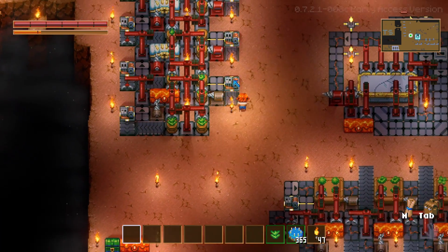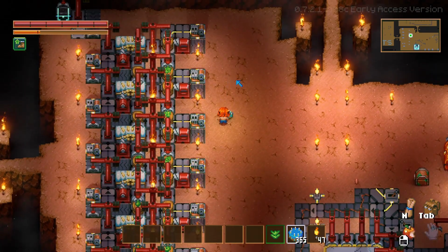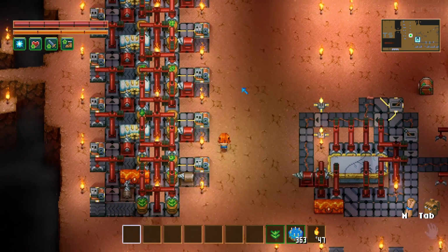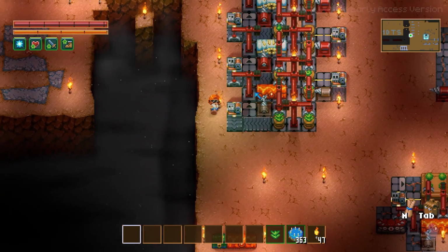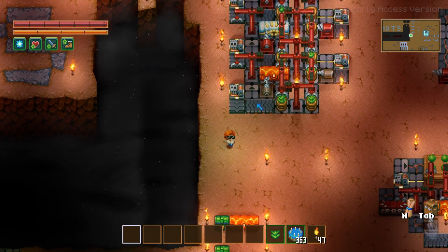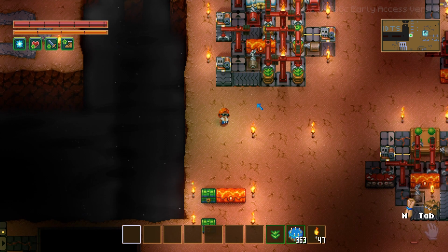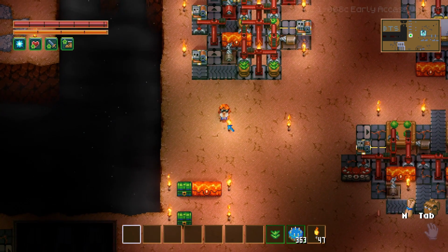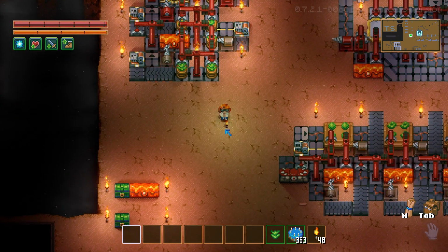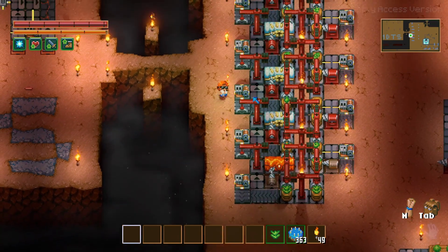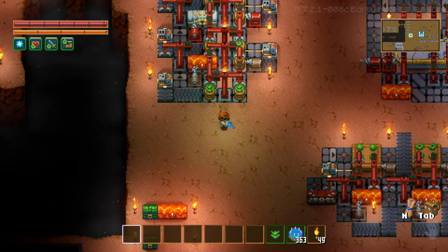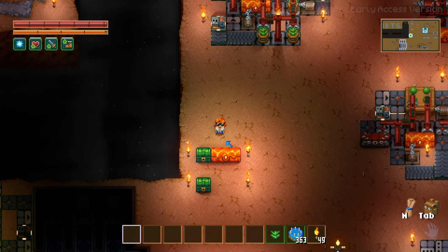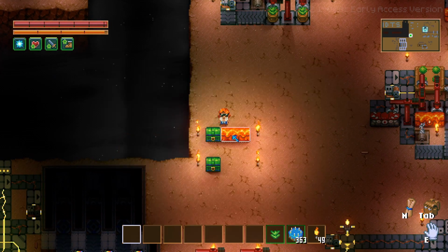Before these filter modules can actually work, however, we need to set up a clock. Now, you are welcome to use whatever clock you want. It should have a minimum of a 3-tick period, I believe. To be safe, I would go with at least a 4-tick period. And it should have a 1-tick on cycle. What do I mean by that?